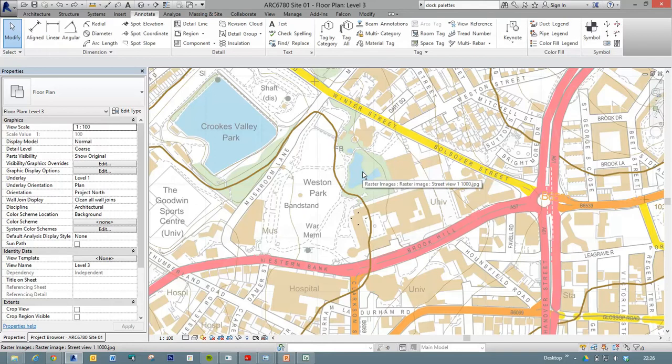is that if you're drawing something which is not a three-dimensional element, then Revit will call that an annotation. And so that could be lines, that could be dimensions, text, some shading, and Revit distinguishes that from model information by calling it annotation.